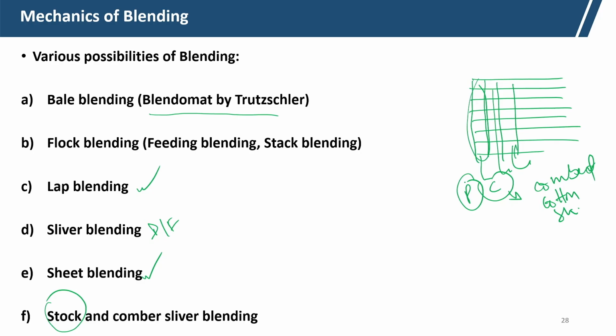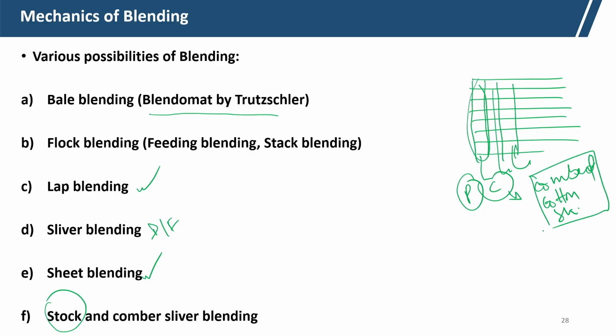Polyester and normal cotton without combing is normally not used in the Blowroom, because short fibers are there, as we have already discussed. Combed cotton fibers are taken here, but the problem is that the cotton fibers are carded twice. This may damage the fiber, and fiber loss will be there.